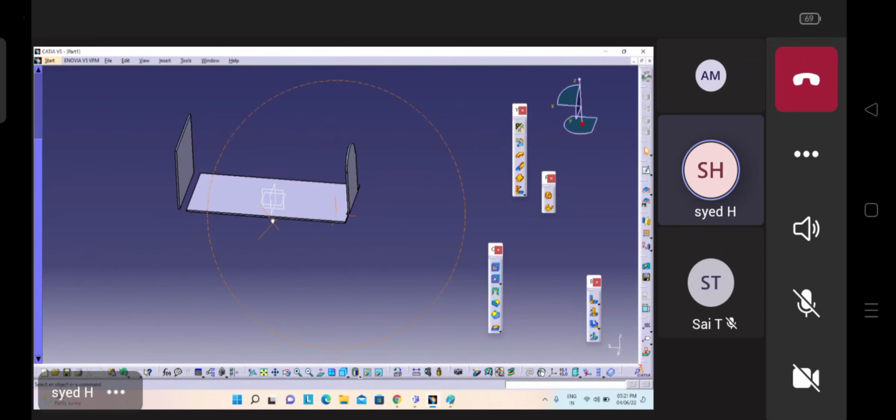Okay, so like that we can create the flanges or wall on edge by using automatic or sketch base. In automatic, it will automatically take a rectangular shape and create the flange. Whereas when you go for the sketch base, here you have to specify or create the sketch. And remember one thing, the sketch bottom edge must intersect with the edge which you selected for the flange. Okay, remember this.